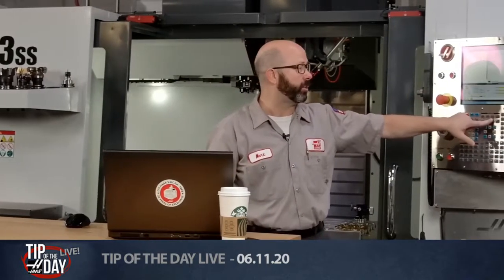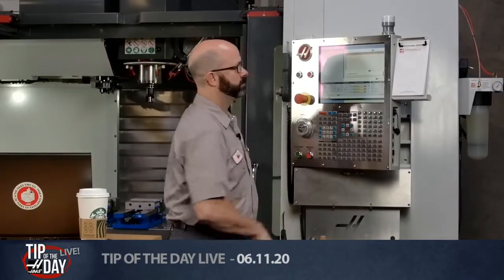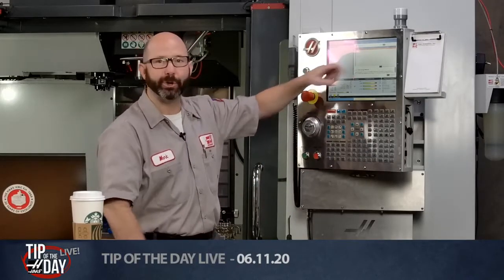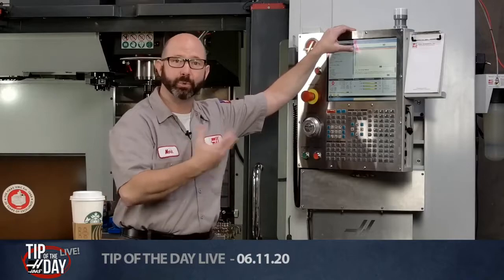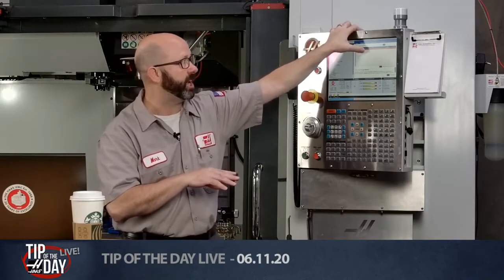On the next gen control, there is a setting 113, I think. I love the next gen control because I forget all the setting numbers now. In the classic control, I had it memorized. On the new one, I just forget because it's got the search function. I'll go to Tool, T-O-O-L, press F1, and it'll search through all that stuff, and you'll find all the settings that relate to the tool or the tool changer. You'll find setting 113 that says Tool Change Method.